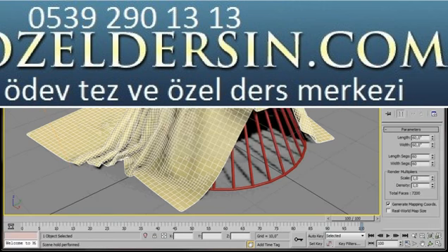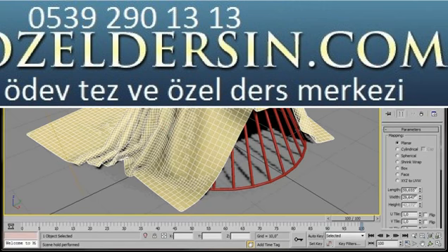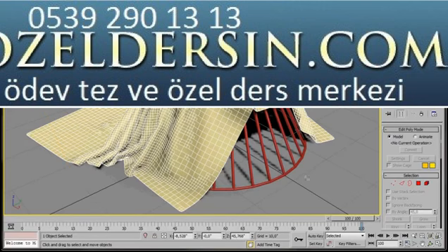There we are, we've come back into the bottom of the stack and now we're inside the plane parameters. Okay, the length and the width was 60 by 60. So now we can come back to our UV map and type in 60 for a length and 60 for a width. Now we need to change the position of the UV map in the stack. Click and hold and we'll drag it down so it's on top of the plane and beneath the cloth. There we are. Okay, let's go back and click on the edit poly, which is the top of the stack.